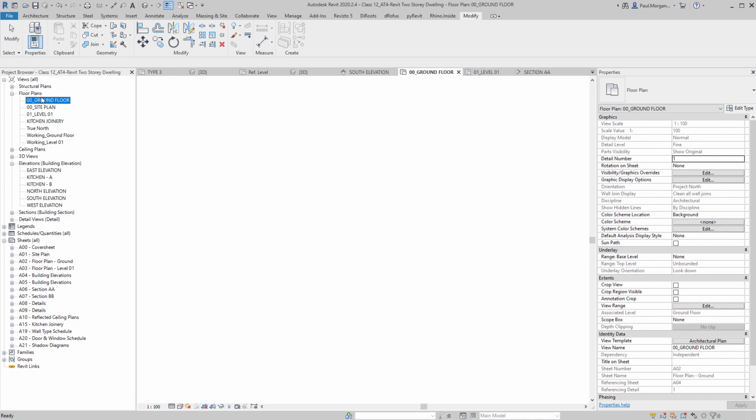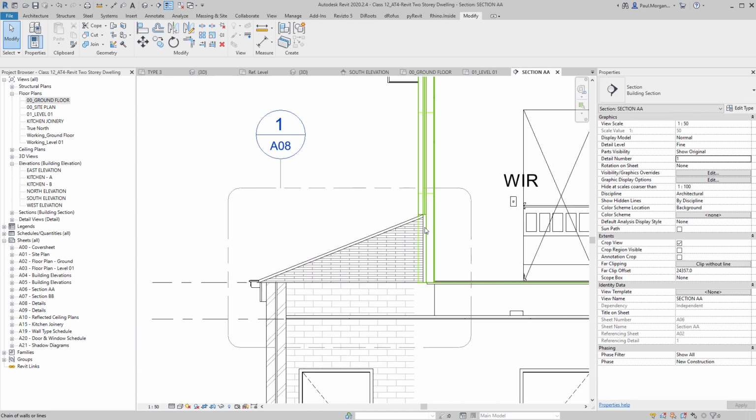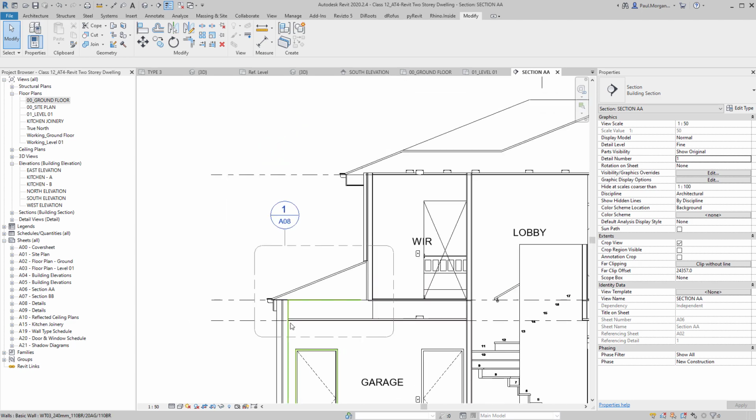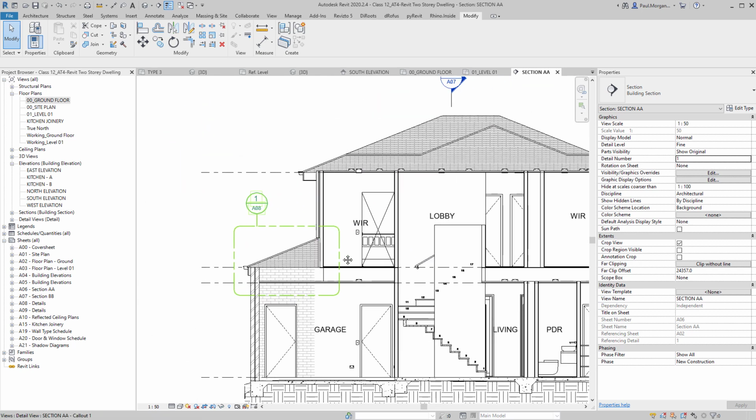Now, again, this is just one example of where you can use void extrusions to your benefit in quite a finicky, detailed modeling sense, like here. But you can use void extrusions basically anywhere on the building at any time to create full penetrations through a wall, or to create rebates like we've just done now. It doesn't really matter one way or another, and that is applicable to ceilings, roofs, basically any system family. It won't do it for windows and it won't do it for doors, but it will do it for floors, ceilings, roofs, walls, etc.